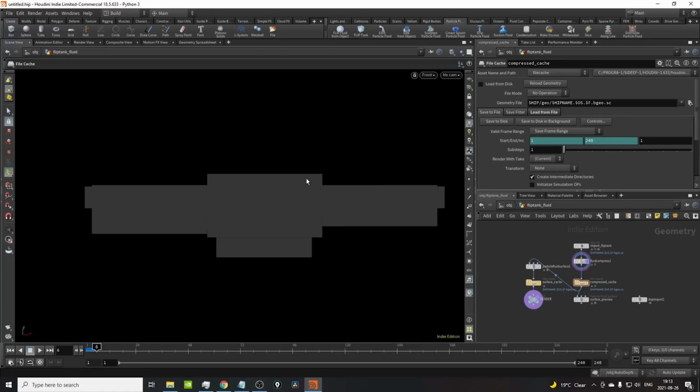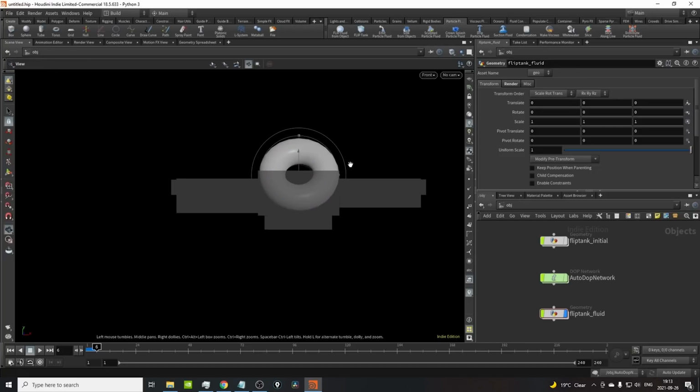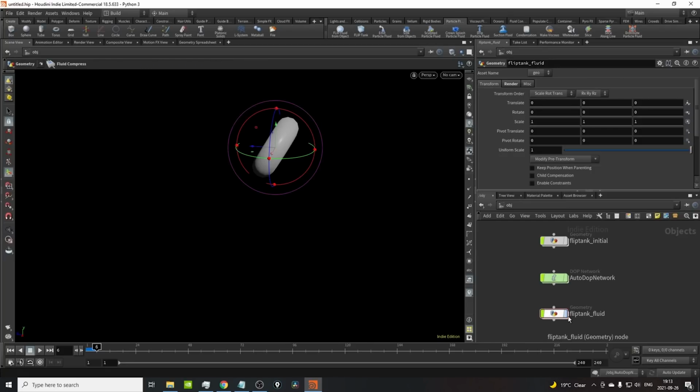Alright, so in this video we covered the very basics of flip simulations. We looked into creating a flip tank, making sure we understand the resolution settings, what all of them mean, making sure we know where our boundaries are set up, what a narrow band is compared to a normal simulation, and also how we can cache effectively the simulation to disk after we introduce some collisions. I hope you all learned something, and yeah, in the next video we will be talking about meshing the simulation.